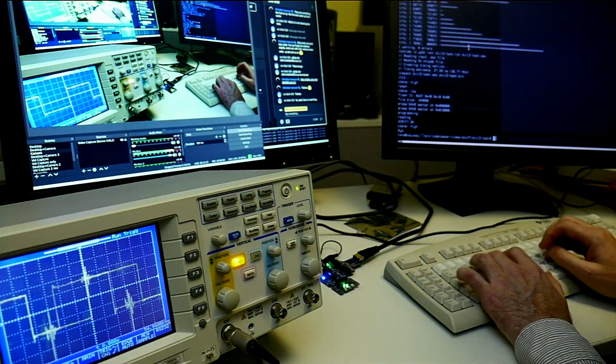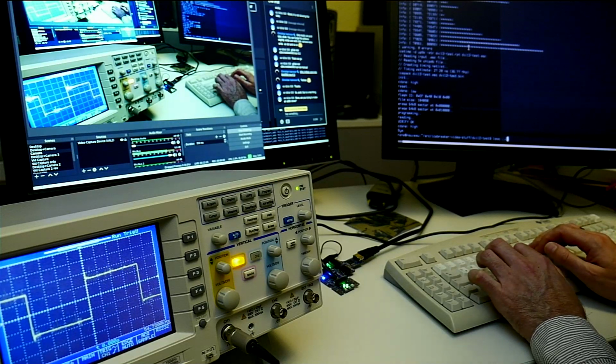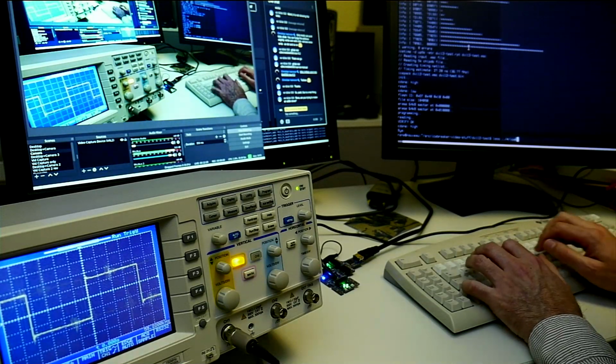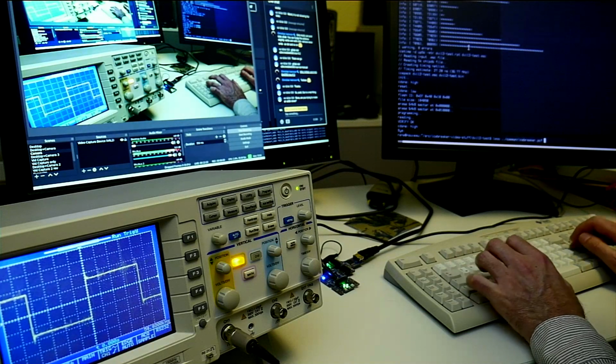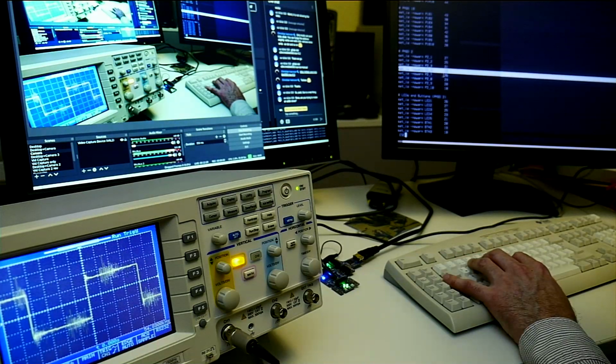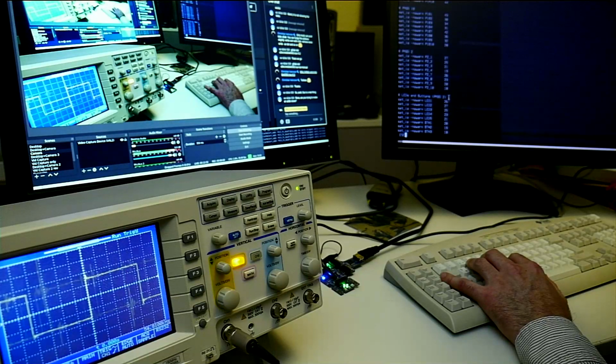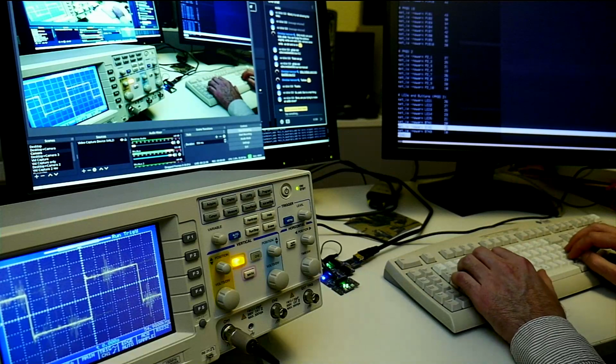We could actually check this here in the Icebreaker PCF, and so PMod 2, pin 4 is pin 19 on the FPGA, on the iCE40, where usually button 2 is connected, so don't press a button now.